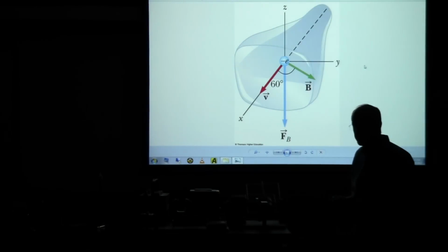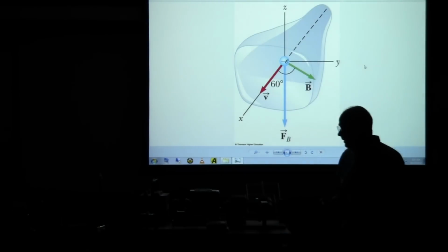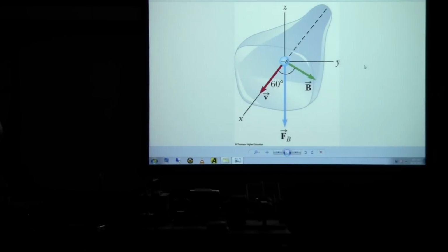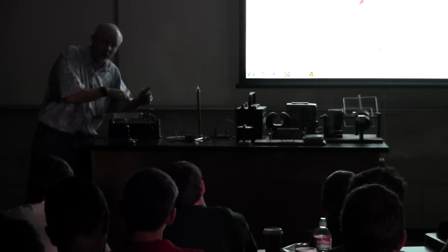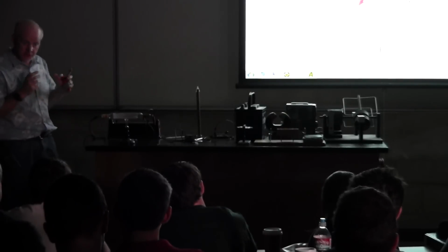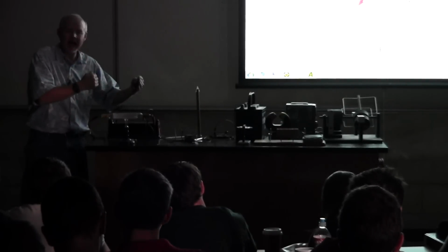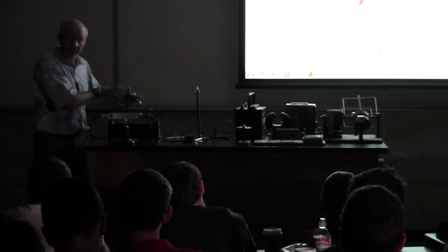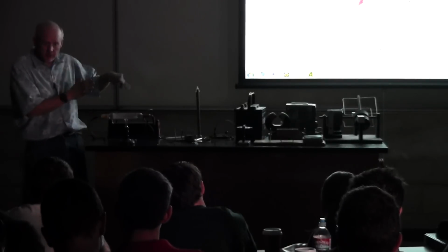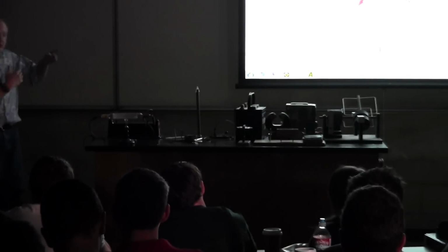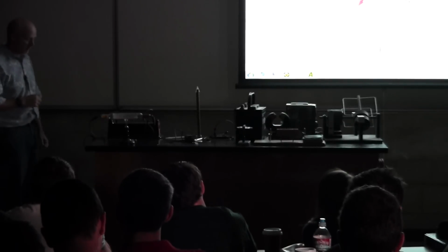What happens to the electrons after they hit the picture? Well, in this case, so many will accumulate that they will move, and it's not paper, it's actually metal with phosphorus on it. So when they hit, they're embedded in the metal, so they conduct along the metal, and in this case, way over here, they come off and they finish going over. So they make a full electrical circuit, if you will, where you might say this is a very high resistance. So 10,000 volts, maybe divided by 10 million ohms, and that would be the current in there. But it's a full circuit, and I just have some resistance.